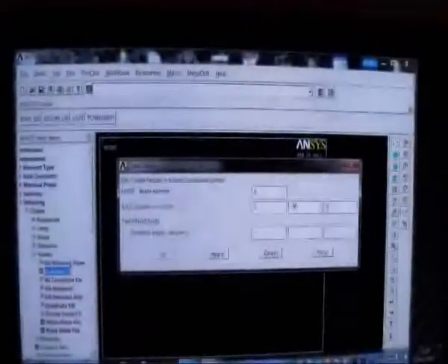So I press OK, apply, and then I pick on node 6, which is at the top end of the element, and the radius is 5. The angle is minus 90, and the position of this is 1 meter. I'm making the element 1 meter long. That's 1 meter there. And then pick on node 7, and the angle is minus 75. The radius of course is still 5, and the Z direction along the meridian is 1 meter.